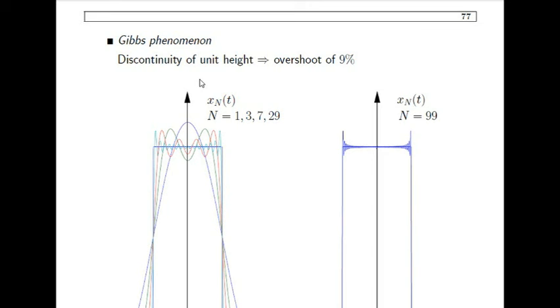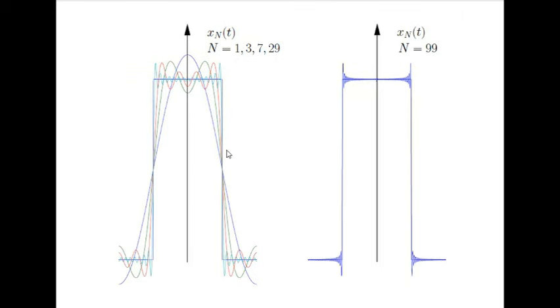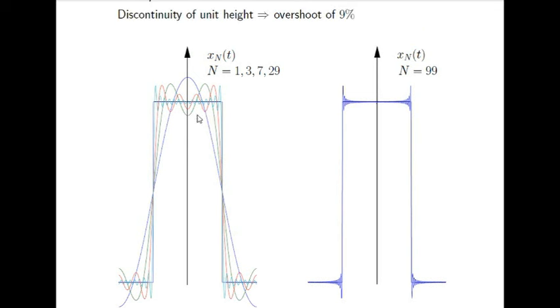So we have a signal x_N(t). When we are increasing our value of N, the signal is starting to compress more. It is starting to flatten in the middle and something more at the corners. This is for 4 values of N and this is for 99. You can see that it is starting to feel something like a square wave, and if we increase the value of N more, then we will get somewhat of a square wave. So this is what the Gibbs phenomenon tells us.